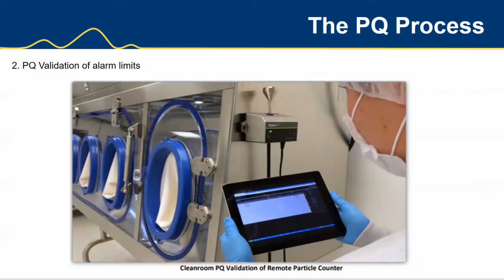You'll see a spike, and you should see a 0 impact on the viable counts, providing the system, the sterile air, and the operator are effectively gowned up properly, no skin exposed, no rips in the gloves, etc. And you should see 0. Then you can also go in and purposely have your operator exposed skin, have a rip in his gloves, have his sleeve exposed, and then look at the correlation.